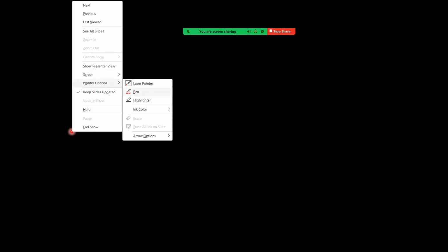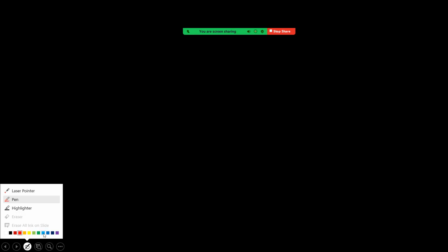So first focus what is barometer. It is one instrument used to measure pressure of atmosphere. Let us see how to calculate pressure of atmosphere using that. So we are taking one glass tube. Its length is 1 meter. So taking a glass tube, length 1 meter. This is now completely filled with mercury.